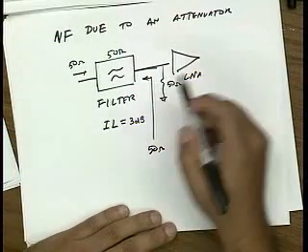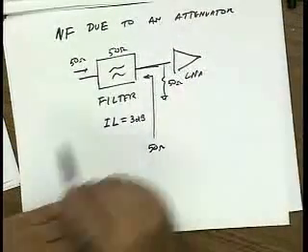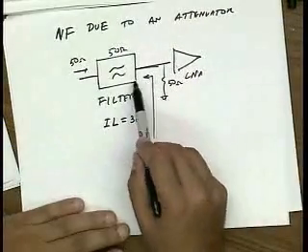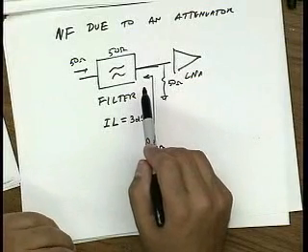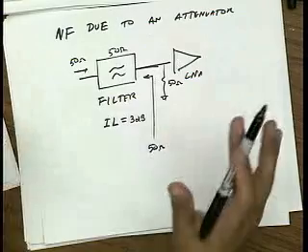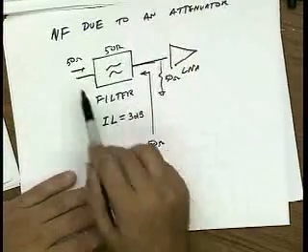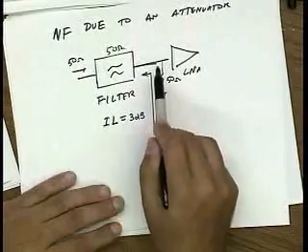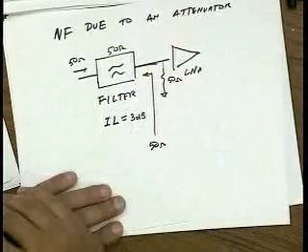In other words, the way to think about this problem is that the amount of noise power that you have is kTB, right? Where k is a fixed number in an impedance matched environment. So this filter hasn't done anything to change the amount of noise. It hasn't actually attenuated the noise. It's just attenuated my signal.